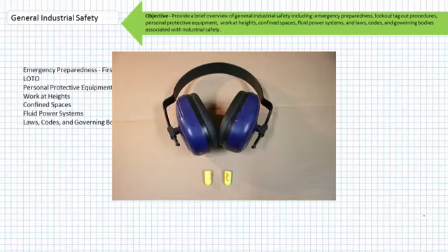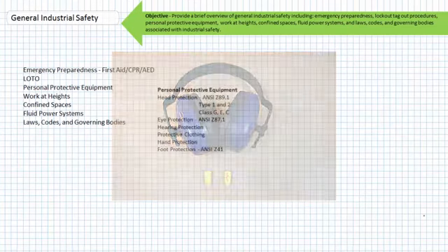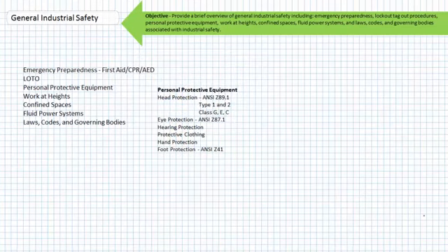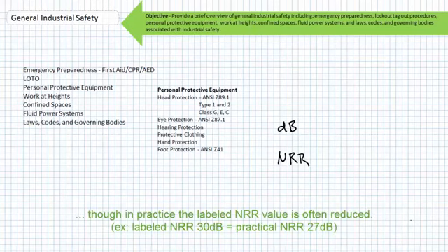An earmuff is an over-ear device. A common unit used to measure sound is the decibel. Both earplugs and earmuffs have a noise reduction rating, sometimes initialized as NRR, that reduces the environmental noise by that amount. As an example, consider a 90 decibel sawmill, and you're using an earplug with a 30 decibel noise reduction rating. This earplug will reduce the sound to 60 decibels.